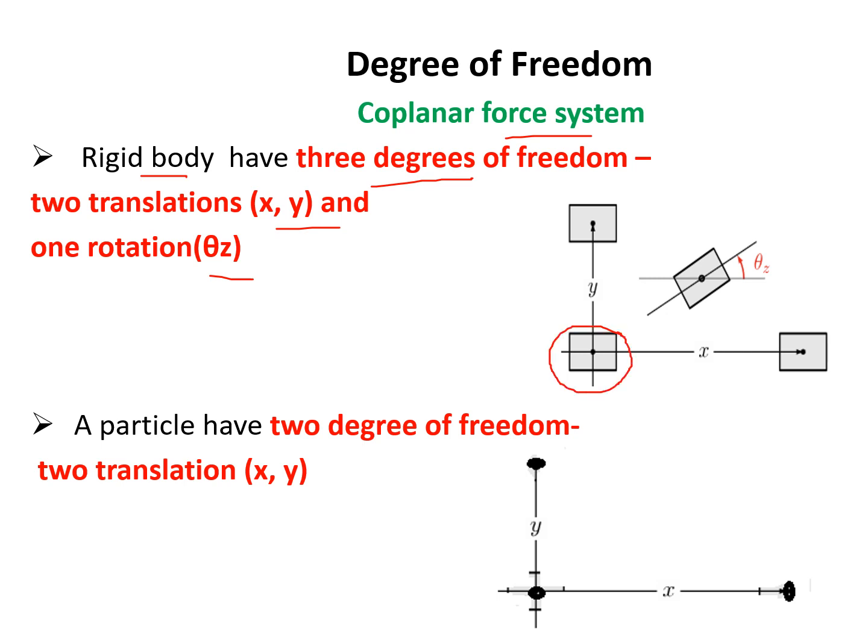So the independent basic ways this body can move: first, the translation in the x direction. It can translate in the y direction, and it can rotate about the z-axis, if you see like this. So we have the 3 degrees of freedom, 2 in terms of translation along x and y, and 1 is the rotation about the z-axis.